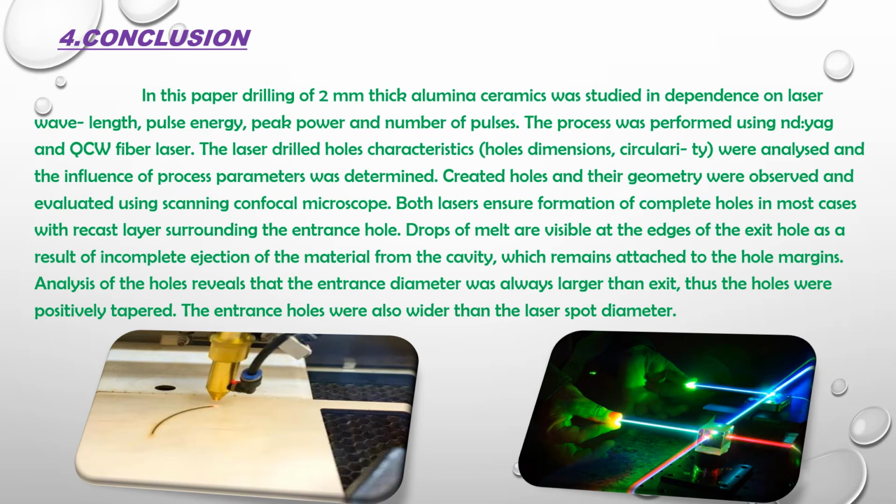Conclusion. In this paper, drilling of 2 mm thick alumina ceramics was studied in dependence on laser wavelength, pulse energy, peak power, and number of pulses. The process was performed using an Nd-YAG laser and a QCW laser. The laser drilled hole characteristics were analyzed and the influence of process parameters was determined. Created holes and their geometry were observed and evaluated using a scanning confocal microscope.